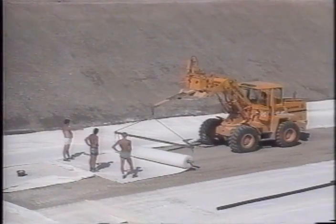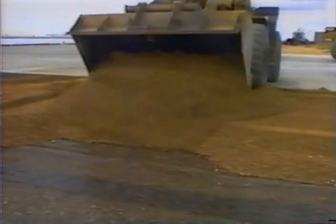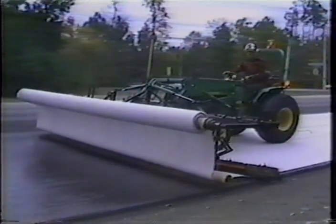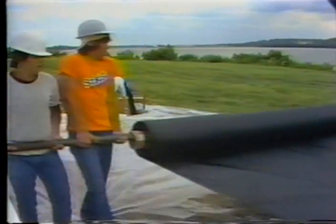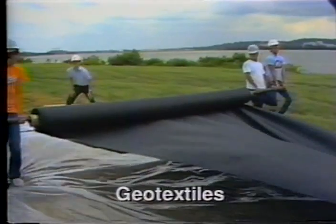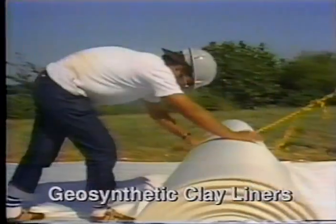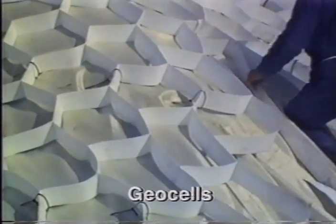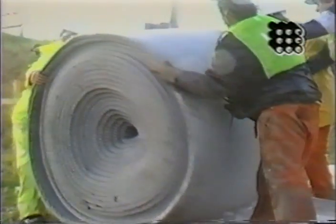Geosynthetics are planar polymeric materials used with soil or rock as an integral part of a civil engineering structure or system. Many different types of geosynthetic materials are now used in the construction, rehabilitation, and maintenance of transportation facilities. These materials are grouped into geotextiles, geogrids, geomembranes, geosynthetic clay liners, geonets, geocells, and geocomposites, combinations of two or more of these materials.